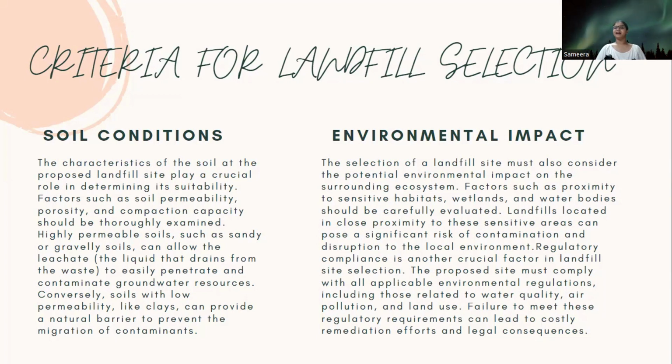Regulatory compliance is another crucial factor in landfill site selection. The proposed site must comply with all applicable environmental regulations, including those related to water quality, air pollution, and land use. Failure to meet these regulatory requirements can lead to costly remediation efforts and legal consequences. These are some of the criteria for landfill selection, among many others.